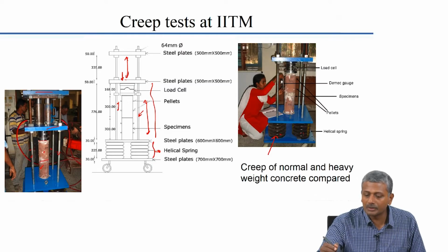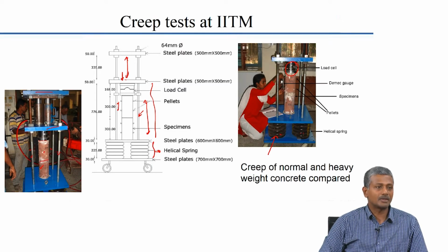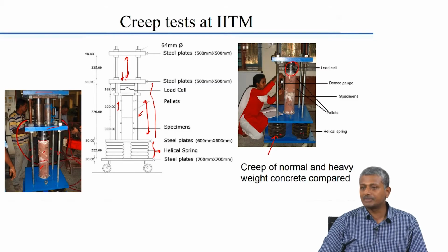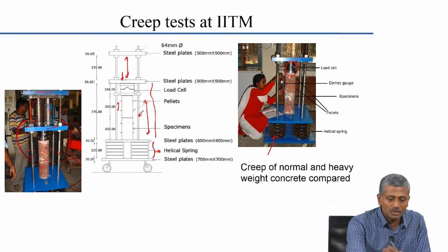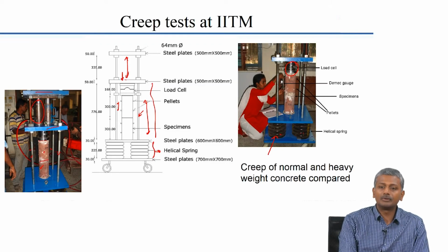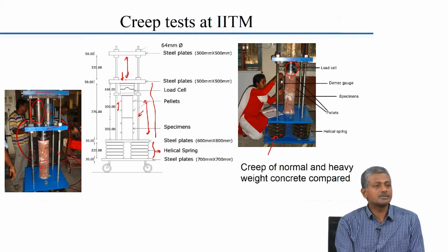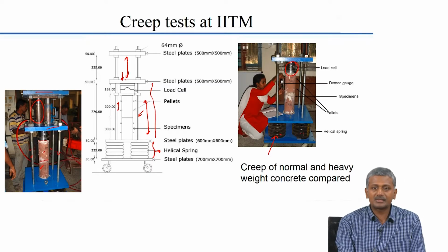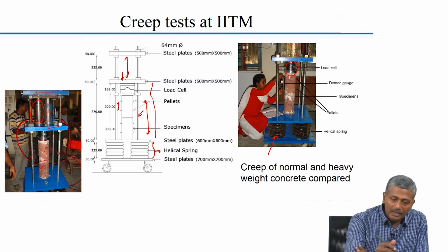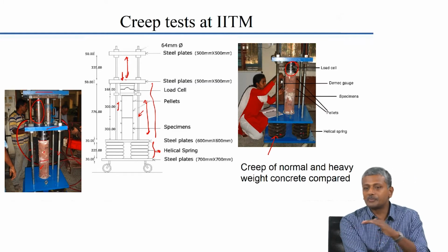Okay, so here the load is being measured on top of the concrete cylinders using a load cell, and that helps us understand whether the system is maintaining the load or not. Right after the application of the hydraulic loading in the beginning of the experiment, you first prepare your concrete cylinders and cure them for a standard duration, typically 28 days, and then subject them to this load, and the loading is applied hydraulically. What you need to ensure is that this load level is maintained throughout.